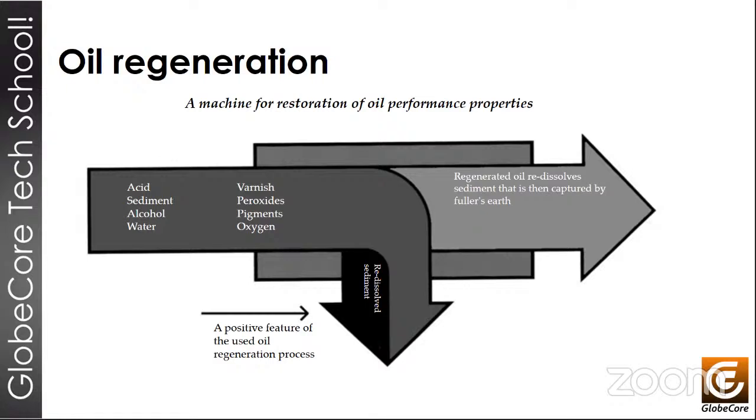And as the oil circulates through the transformer in the process of regeneration, basically we take old oil, we regenerate it, and it goes back into the transformer. It mixes with that old oil, so it gradually becomes clearer and more pure, okay, less acidic. And this oil starts to dissolve the contaminants, the sludge that is in the solid insulation. And as it circulates through the regeneration plant, these contaminants are removed. That's the good thing. However, there's also the bad thing, okay? Because if the oil has an oxidation inhibitor mixed in it, that oxidation inhibitor is also removed. So whenever we regenerate oil and we want to keep the oil inhibited, we must add this inhibitor back at the end of the process, okay? Next slide, please.